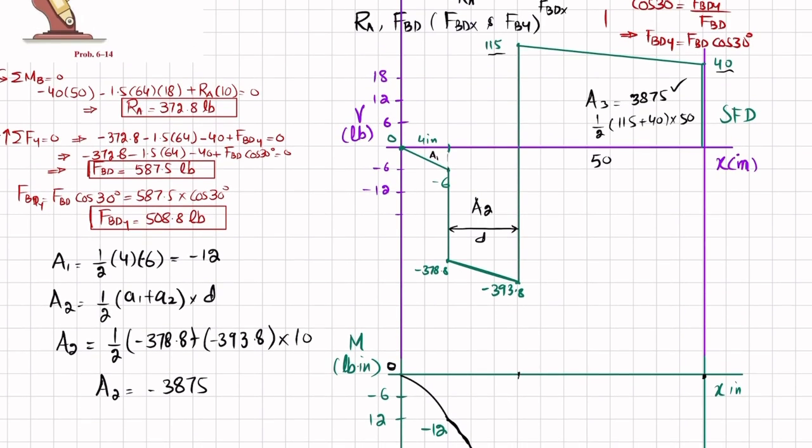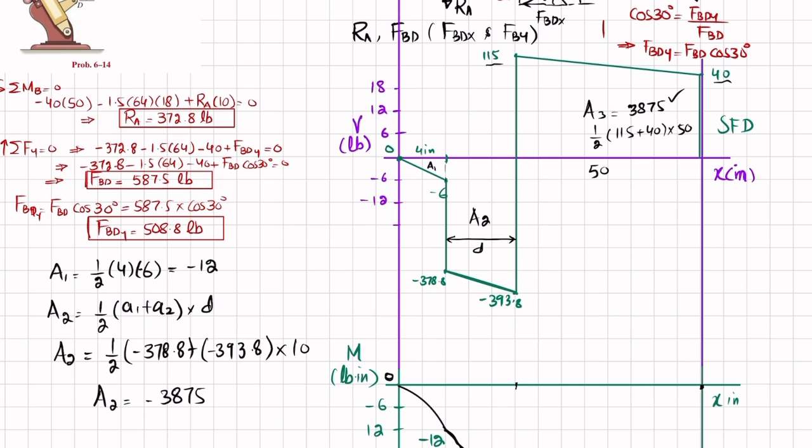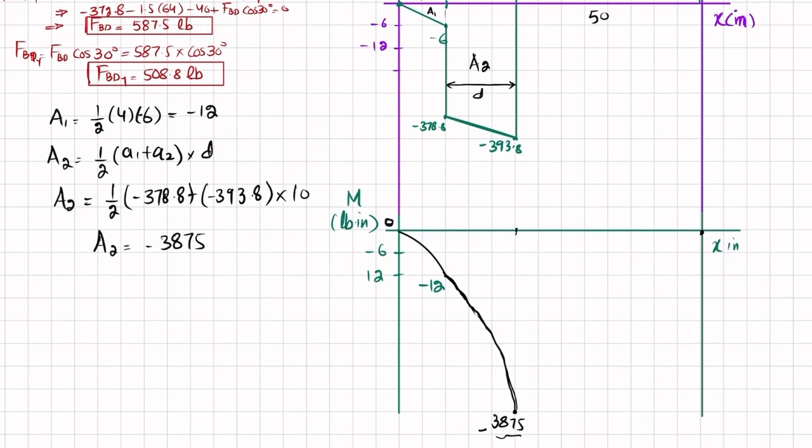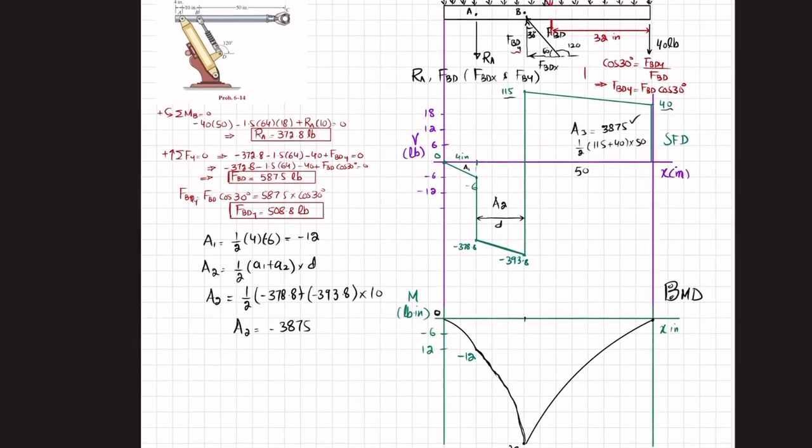And you can see that this area is positive and slope is decreasing. So again, your bending moment will be a second degree curve and it will be in clockwise direction. It will be like this. So this is its bending moment diagram. I hope it is clear.